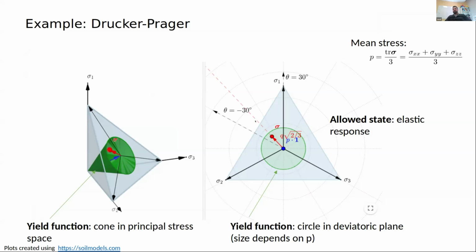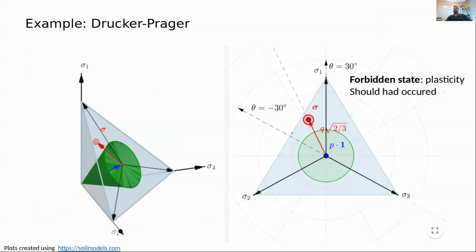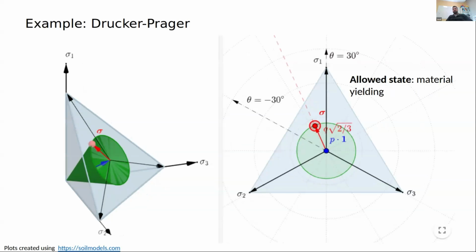We're looking at the same yield surface, but in the so-called deviatoric plane. And stresses that are outside that circle are forbidden. So you can't be there in terms of classical elastoplasticity. In some viscoplastic models, it is allowed to be temporarily out of these, but this class of models is not covered right now. Okay, so what about the hardening?